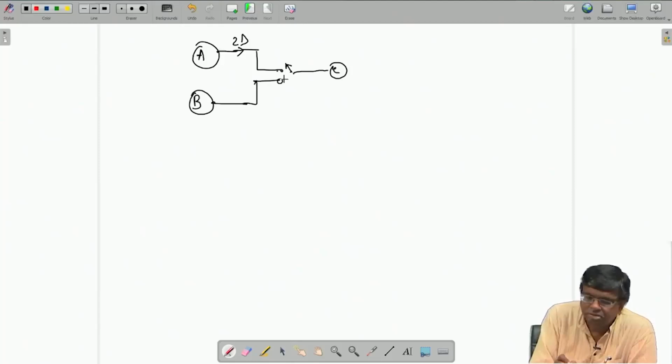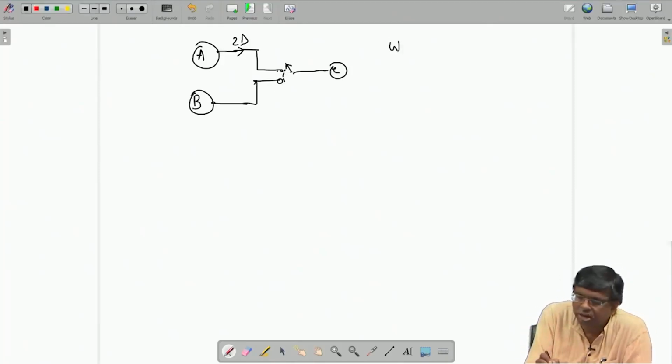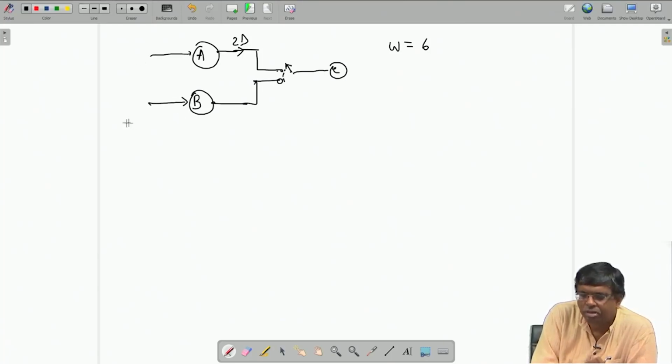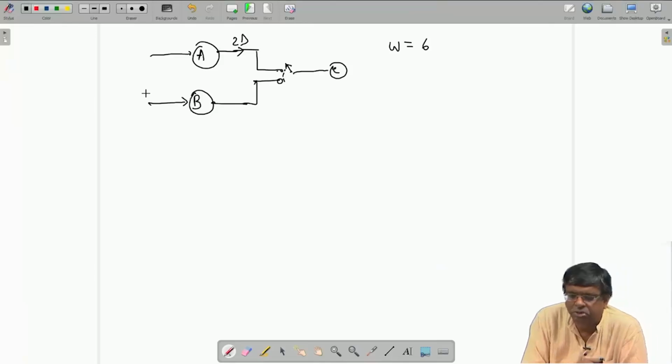It is given that our word cycle here is 6. So, it is a fully bit serial system where the original word cycle was 6. So, 6 bits constitute 1 word. Now, using the faster clock, 6 bits are coming serially down. Every 6 bits constitute 1 word. The clock is 6 times faster than the original input clock, because in one input word clock, all the 6 bits are packed one after another. Anyway, that is a side story.